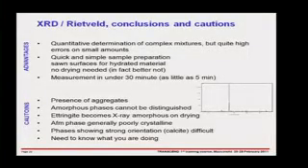So just to summarize on the Rietveld techniques, its huge advantage is you can do these measurements extremely quickly. You can get this kind of quantification for complex mixtures in as little as 10 minutes, but if you want a bit better accuracy, it's better to analyze for, say, half an hour or so. The sample preparation is quick and simple, but that doesn't mean that you don't need to take precautions.